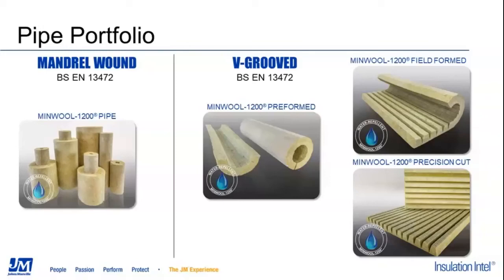Another option for pipe insulation and possibly tank and vessel is looking at the V-groove offering within the mineral wool family. And within the V-groove family, there are three different formats available. The main format or primary format is the one on the top right there called the field formed. And so that is basically taking mineral wool board product of the appropriate thickness. We cut precision grooves in the insulation such that when it is wrapped around the pipe, all those grooves close perfectly and you don't have any gapping or air spacing in there.